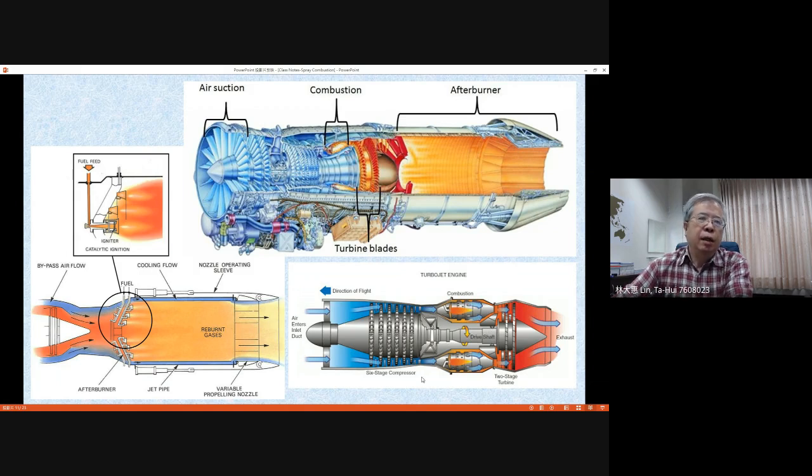As you learned in the Brayton cycle in thermodynamics, some work is produced by the turbine, but that work is just sufficient to drive the compressor to increase the pressure of the air. That connection basically transfers the work from the turbine to the upstream compressor, and you still have a lot of thermal energy left. The high temperature products go to the downstream side.